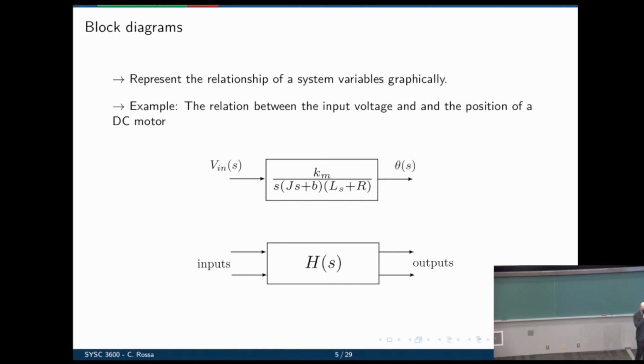So what is a block diagram? We have already used Simulink for one of the labs, so we pretty much have an idea what I'm talking about. The idea is to now take equations and represent them in the form of a block diagram, in the form of a block element that has an input and an output. So in the block, we have a function of S that represents the system. And now this system is given an input. We pass that through the transfer function or through whatever equation goes in there. And then we have the output on the other side.